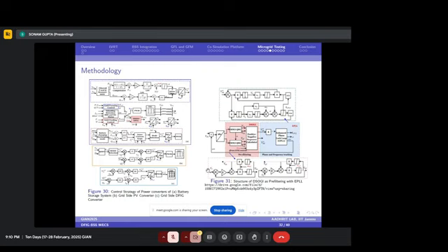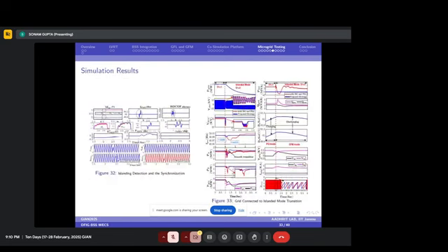So the grid forming control is generating the voltage as well as the frequency reference, and that frequency reference is given as one of the inputs to this EPLL, instead of the frequency coming from the enhanced PLL. This way it will be implemented for grid connected operation as well as when transiting from grid connected to islanded mode operation.